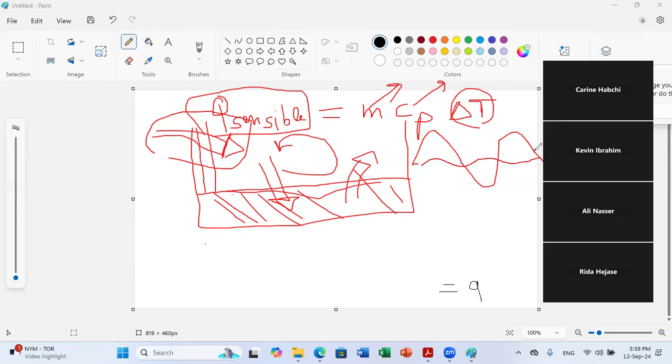So here also, to design appropriately the thermal mass, we need to start from a basic equation of heat transfer, which is that the sensible heat stored is mCp delta T. And then depending on the amount of heat that will come in your environment, you can do appropriate design for what is the mass needed in order to allow you to have a stable temperature in your inner environment.